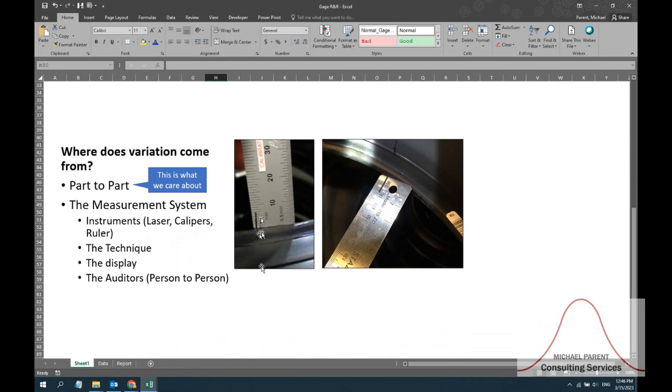These are bead vents over here on the right. And what these bead vents can do is if they get excessively long, they will actually slowly deflate the tire. They sit right here where that tire meets the wheel, and little by little air can escape if these things are too long, and they don't get a good seal of the tire on the wheel. And then over time, that puts the customer at risk, and they don't really like to see a flat tire when it's a brand new tire, right?